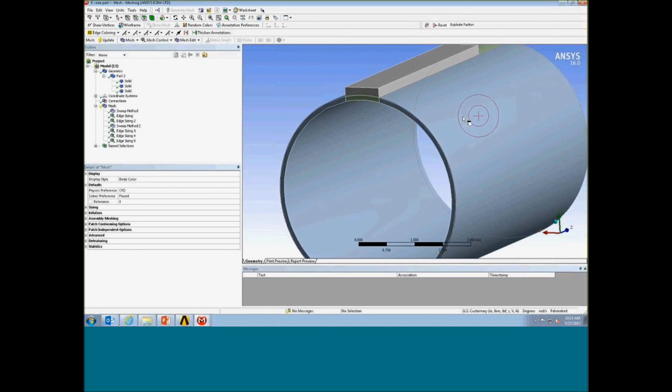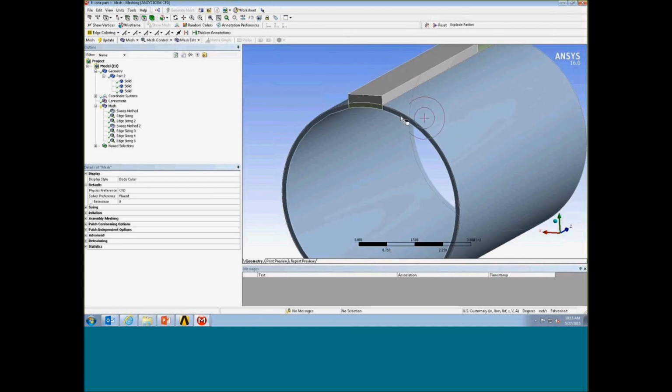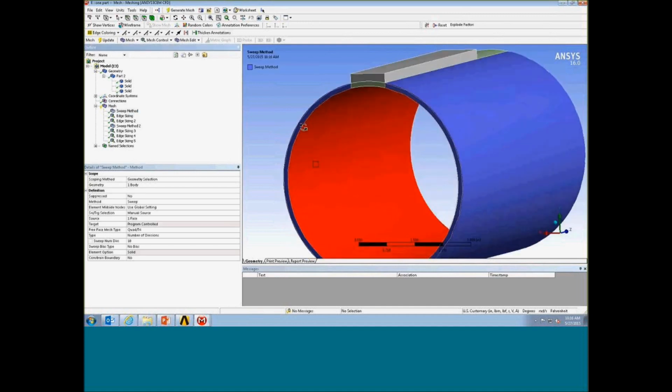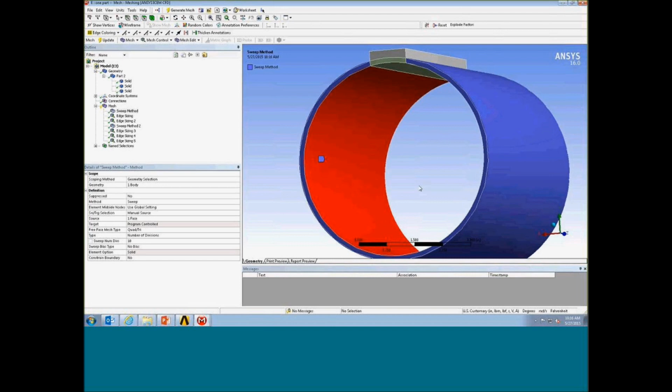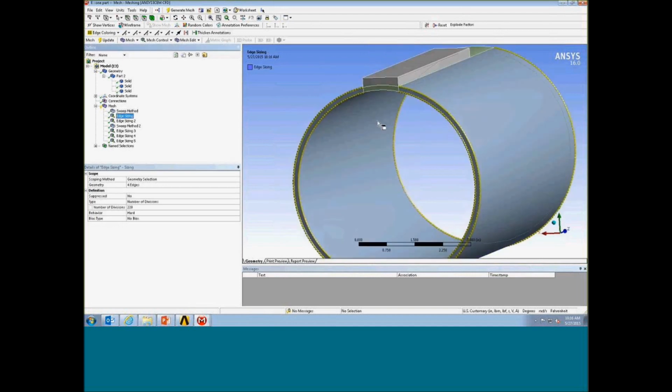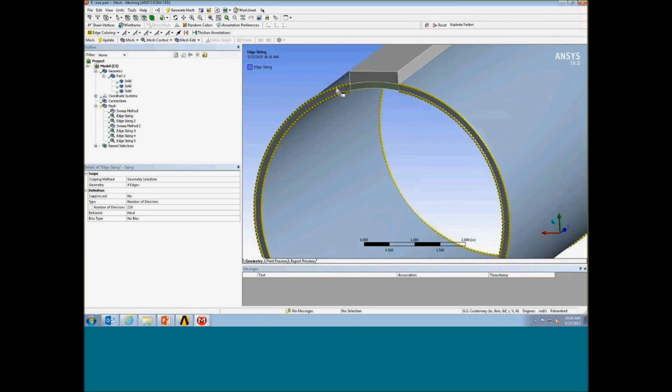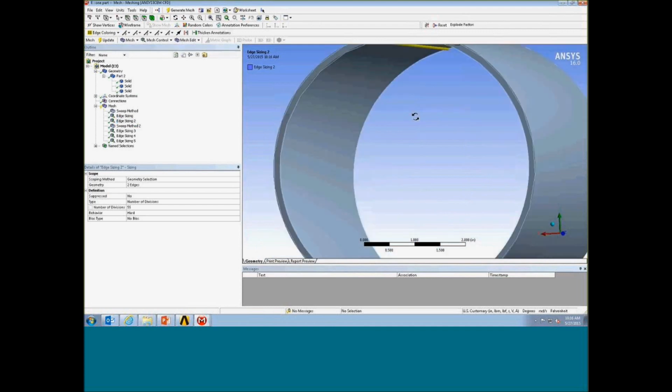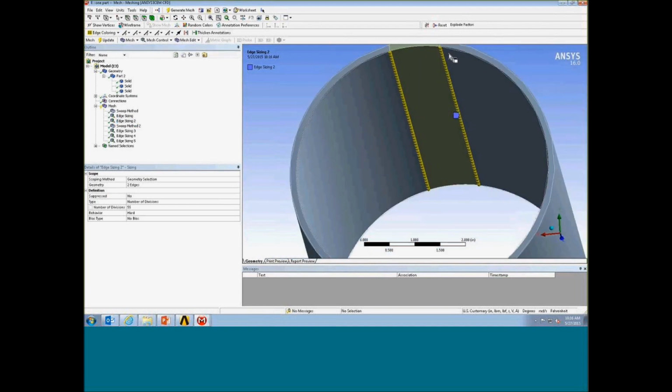Since now we divide the flow domain into 3 parts, all 3 parts become sweepable. If you look at the meshing setting that I have here, I set up a sweep mesh for the majority of the circumference region, and I have set up edge sizing. I can control exactly how many elements I like in the circumference direction, right? In this case, I have 220 elements.